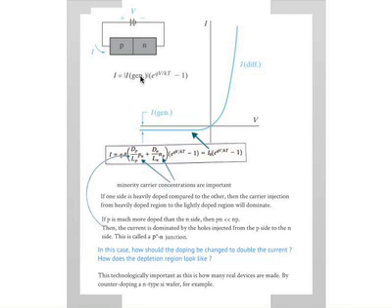It's the majority carrier injection from the majority carrier side to the minority carrier side, and then recombination. So the source is actually thermal generation. In other words, you have to generate electron-hole pairs here for this electron to come across, essentially.